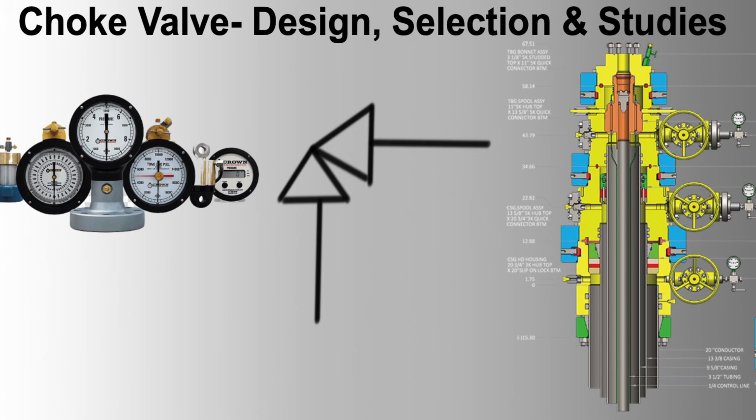2. Deep water drilling. Type hydraulic choke valves. Scenario: high-pressure deep water drilling operations where precise control is crucial. Advantage: high precision and control over valve operations improve safety and efficiency. Disadvantage: high complexity and potential for hydraulic fluid leaks increase maintenance demands.